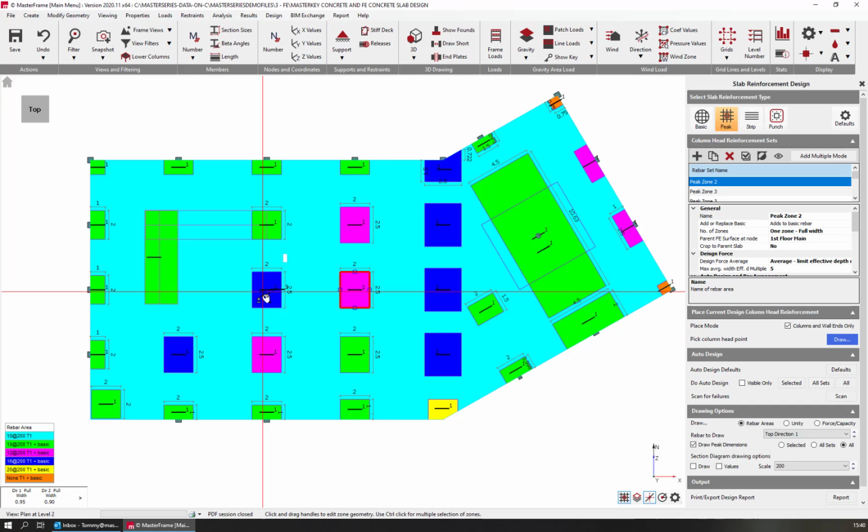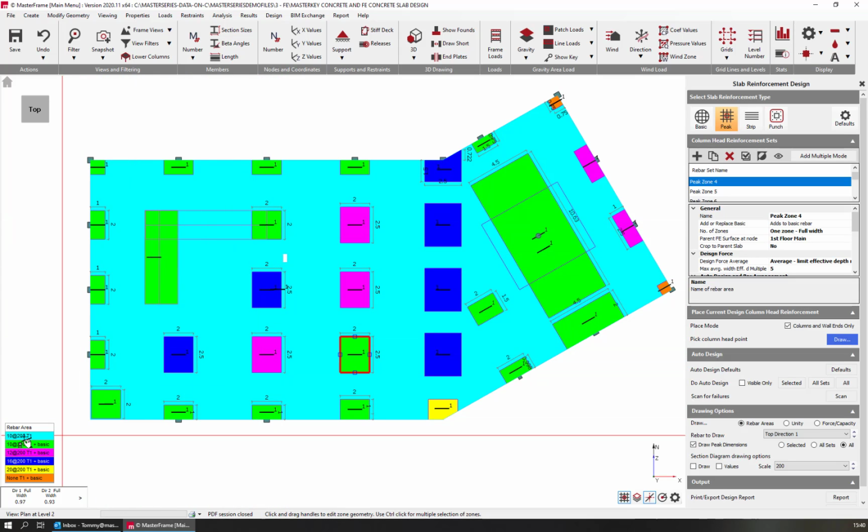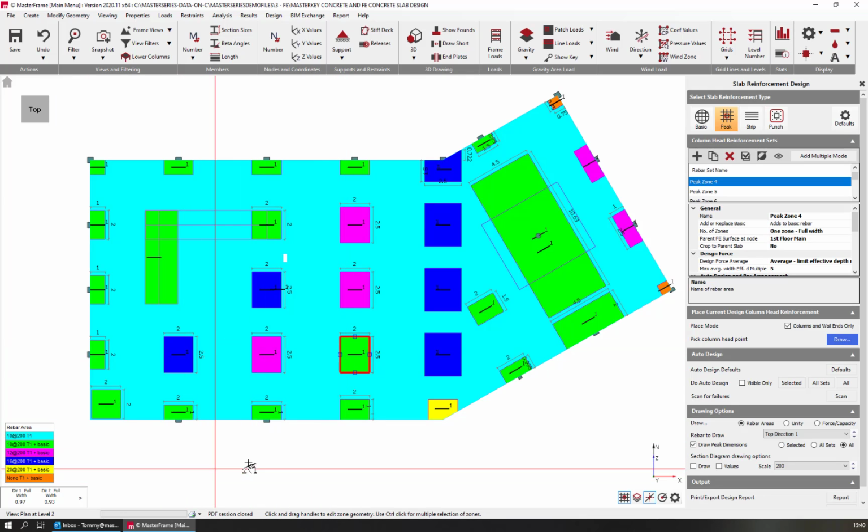I need it a bit heavier. And this is down to 10s at 200. Well, you might decide just to make that at least the 12s at 200 to have a consistency around there. And you can rationalize that, and these need to be heavier for the awkwardness of the column corner. So you can rationalize your reinforcement, your size of your reinforcement, as well as the overall patterns, so that you have as few different patterns.